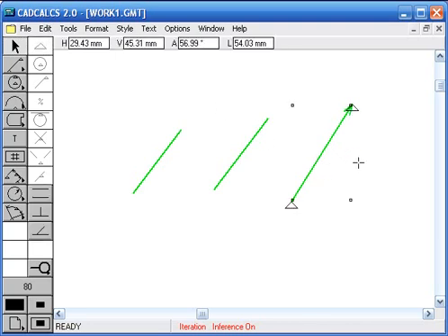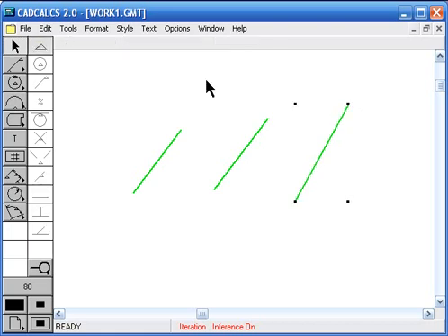If you just want to constrain a geometry, you can allocate a value to this value bar. For example, I want this angle to be 60 degrees. All I have to do is press the A key on the keyboard, the corresponding key to the value bar. The value bar gets highlighted, and then I can enter 60 degrees and the line is at 60 degrees.